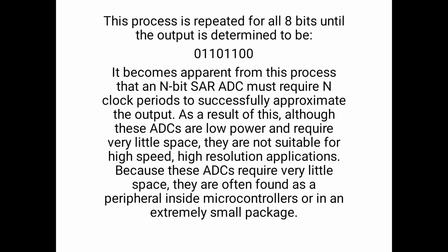This process is repeated for all 8 bits until the output is determined to be 0, 1, 1, 0, 1, 1, 0, 0. It becomes apparent from this process that an n-bit SAR ADC requires n clock periods to successfully approximate the output. As a result, these ADCs are low power and require very little space.